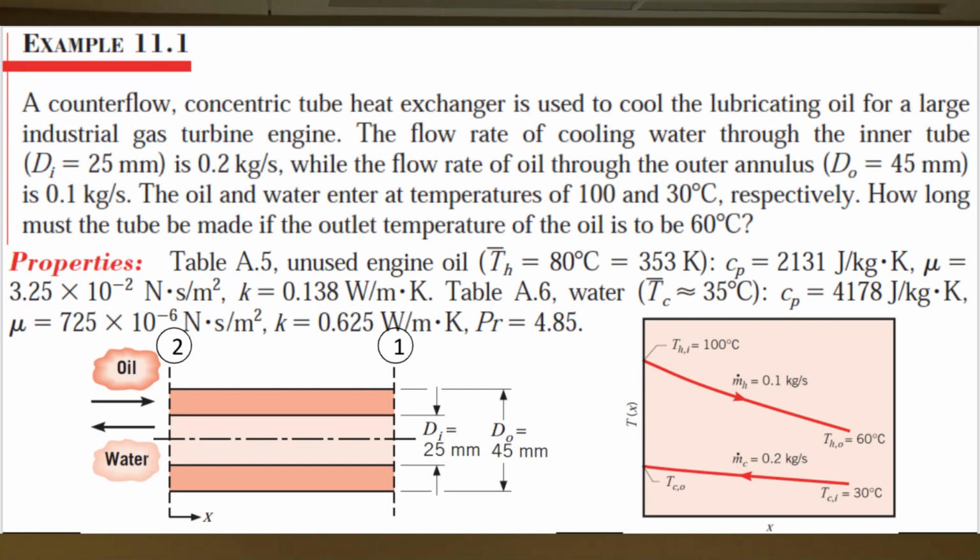This black line here essentially is the wall of a pipe. But they don't give us that. If they don't give it to you, what you assume is what you like, and is what it should be also, that resistance to conduction is negligible, so that the pipe is thin enough that it doesn't matter from the point of view of your calculation of overall heat transfer coefficient.